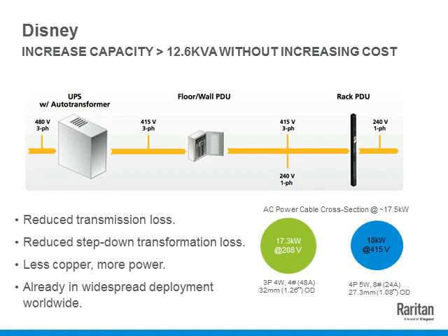So this is an illustration of how you can provide an average of 17 kilowatts in two different ways. If you use the traditional 208 volt three-phase to provide that 17 kVA, you're looking at a 4-gauge wire. So that's a lot of copper. What we're showing here is the outer diameter of the inlet cord itself.